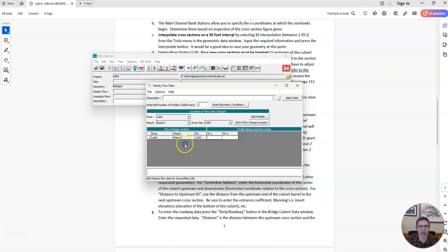And when I do that, now here in the reach, this is PF1, which I think stands for profile of flow 1, and then profile flow 2. What I enter here is at river station, what's the flow rate? At river station 1000, what's the flow rate? Well, one flow profile is 20 CFS. That's my existing flow rate I was given. And the other is 100.